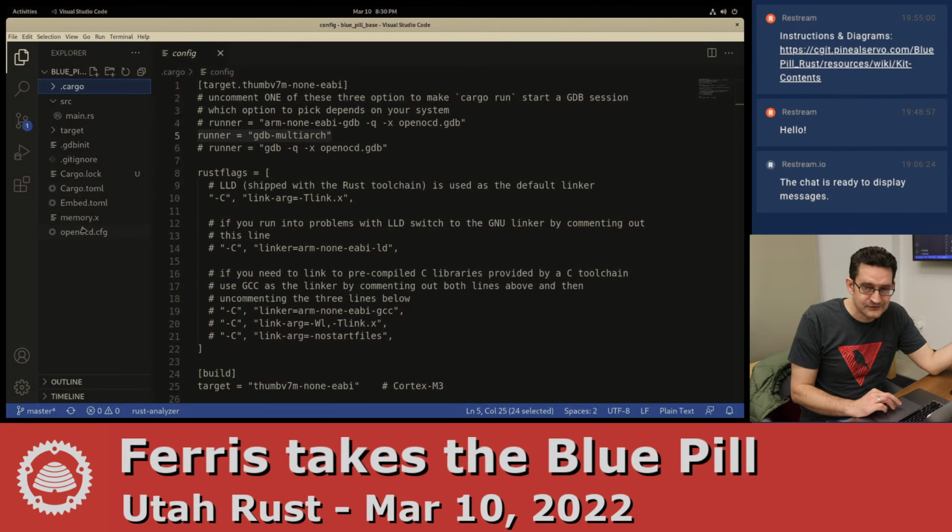Last time we did this, the tools that we were looking at, like cargo embed, had limited GDB support, but you couldn't use it at the same time as the RTT support that allows you to print things out. So it's easier to get started with printf style debugging. Yeah, we had to use OpenOCD, and that was a whole other setup mess. So anyway,